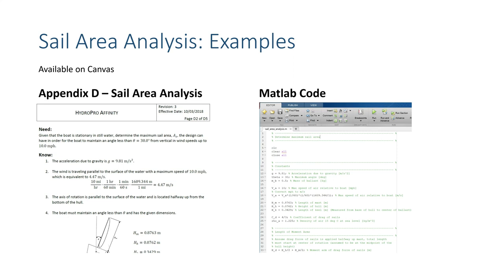And if you have it times a length, you've got a volume. And so as it pushes down in the water, as it tries to tip, that volume is increasing. And so you're actually increasing the buoyancy on that side. And so that's how you keep your boat from tipping over in the case of a catamaran. Whereas in a single hull design, you don't have that moment arm from the center point of a catamaran going out to the separate hulls.